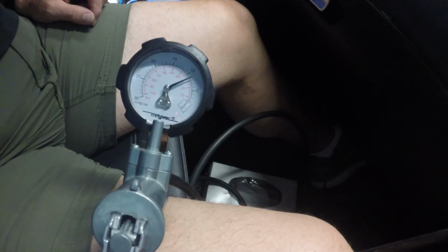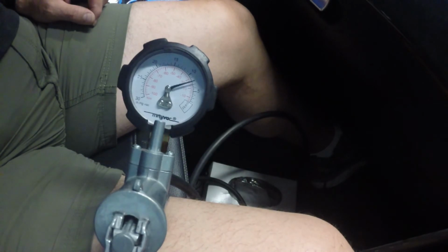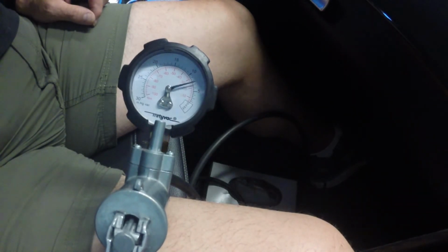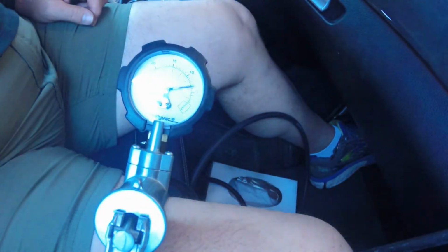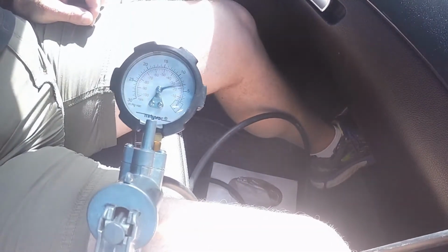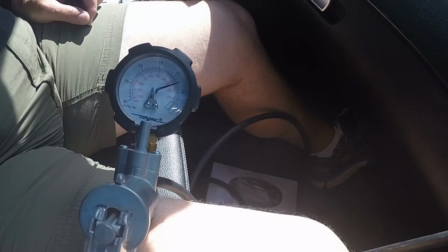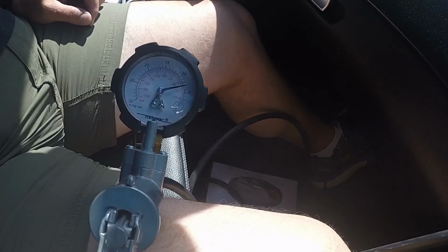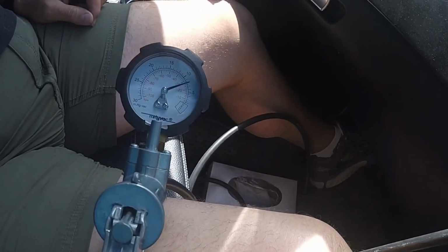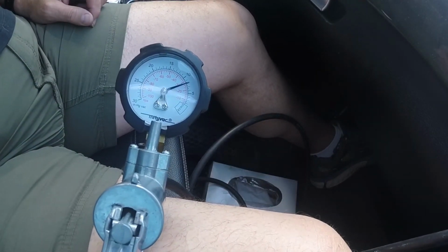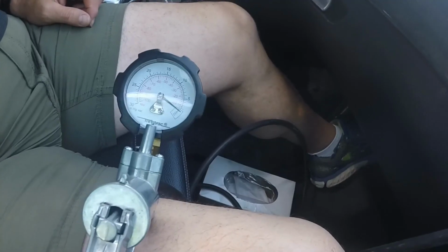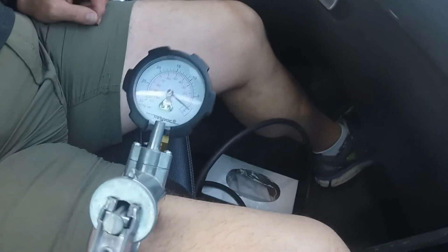So this is our road test with the vacuum gauge hooked up to the right side turbocharger. It's not really making a whole lot of vacuum. I'm not sure what that means yet, but we're at less than 10 inches of vacuum here, which doesn't seem like a lot to me. In a second here, we're going to jump on this thing and see what it does. Now we know the car's not producing boost, so let's see what it does when we step on it. The minute we step on it, the vacuum goes to 0.